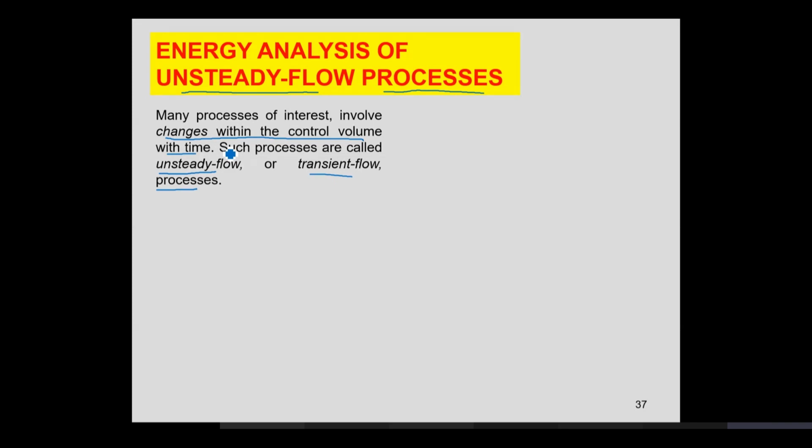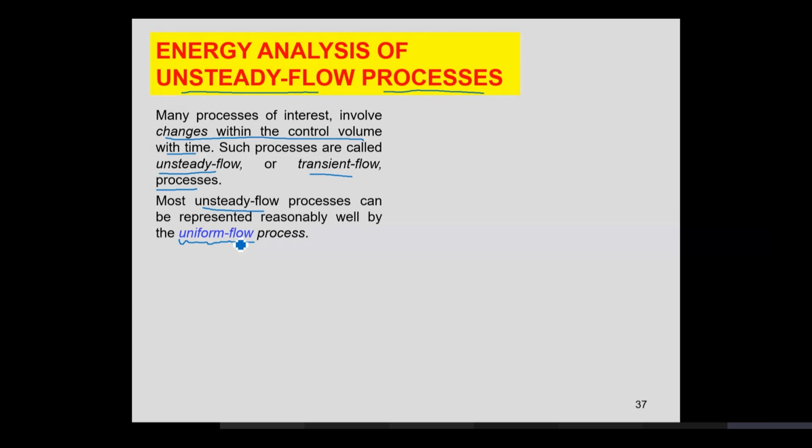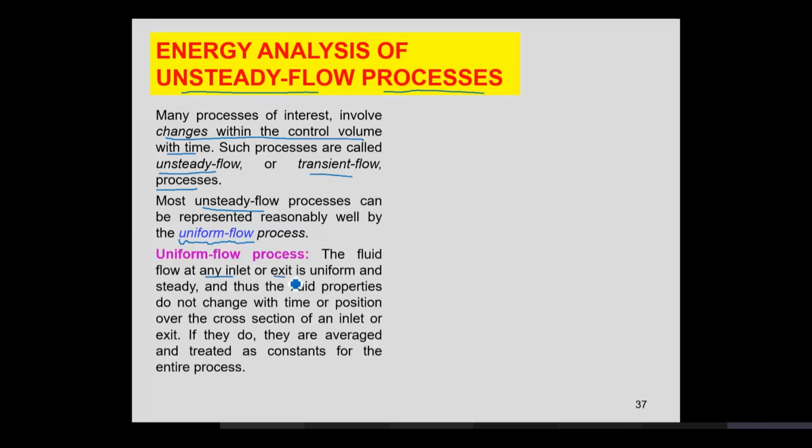We'll deal with a specific case of unsteady flow processes or transient flow processes, which is uniform flow processes. It says that most unsteady flow processes can be represented reasonably well by uniform flow process. In this process, the properties at the inlet and exit essentially do not change with time. So the inlet or exit is uniform and steady.